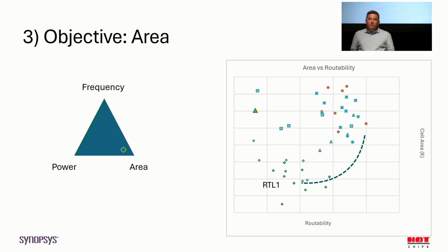Okay, so through this example, we can see how we can apply the optimization paradigm not only in specific design abstractions like layout, for example, but across design abstractions. In this case, we looked at how we can take pre-synthesis RTL all the way down to layout and create a hierarchical search system that allows you to consider the relative benefits, again, for PPA in this case, across the entire abstraction stack that we traversed, from functions to gates to layouts.